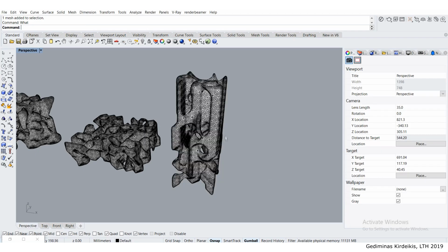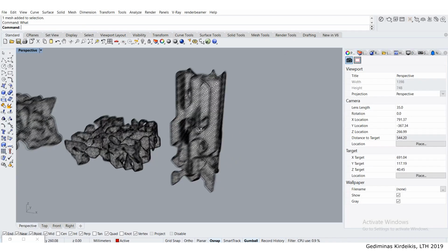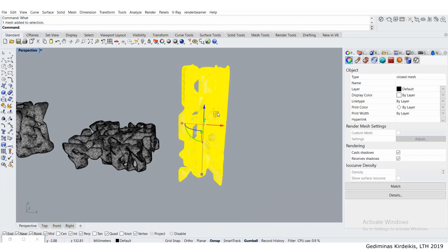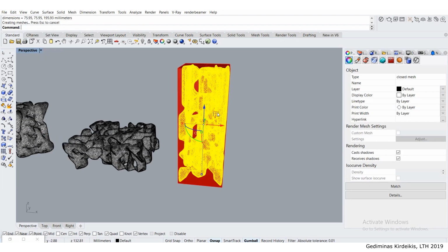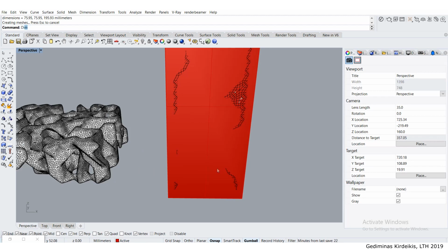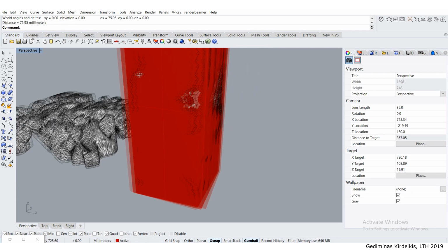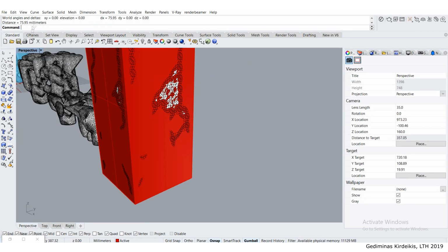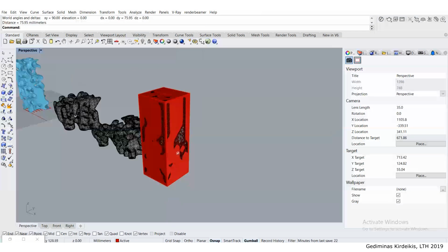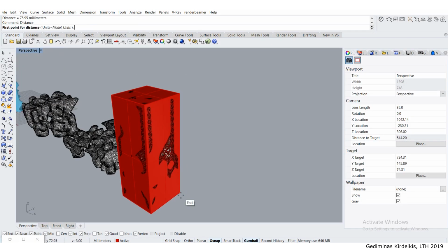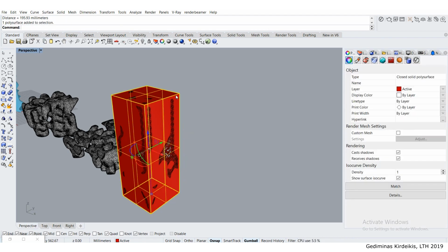Okay. And also I'm going to check this guy's bounding box. So I'm just going to type in bounding box. I'll type in distance and just check. No, we have 75.95 millimeters, and this is due to meshing. It increases the size of the bounding box a little bit, but that's fine. 75.95, same. So basically 76 millimeters, and the height is 196 millimeters. So that's fine.